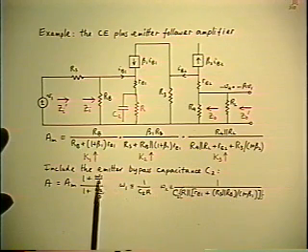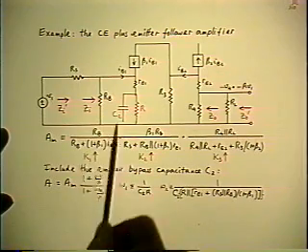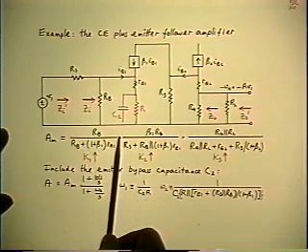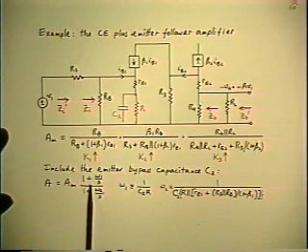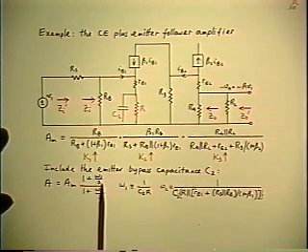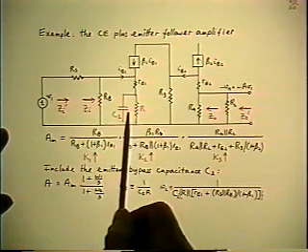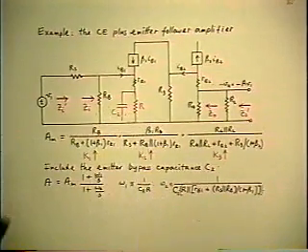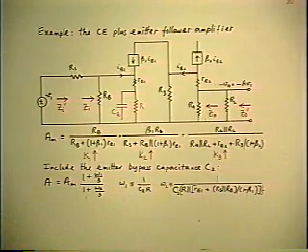We know the pole and the zero are going to be in inverted form because the reference gain is the high frequency limit. So the correction factor is of the form 1 plus Zn over Z. The Z is in the parallel combination. So that's how you can write down the factored pole-zero form in the answer, by doing the entire application of the theorem mentally.